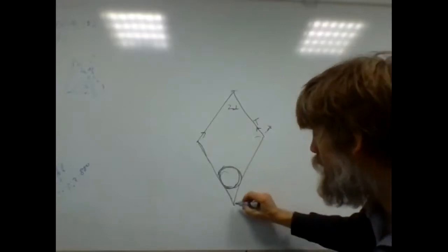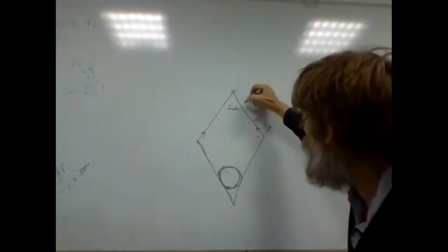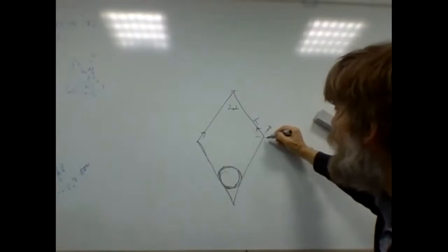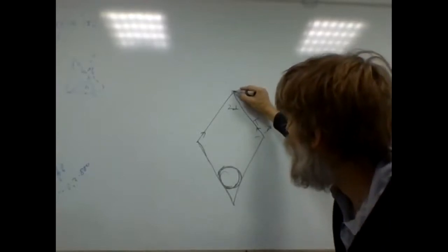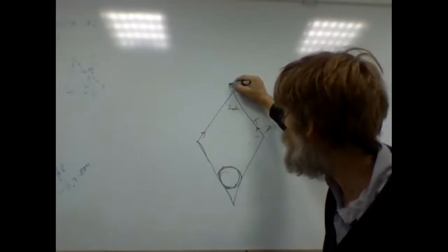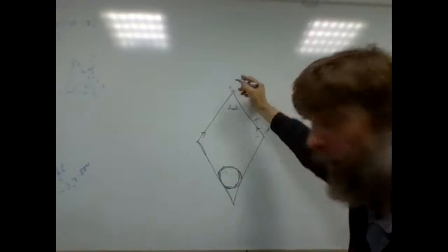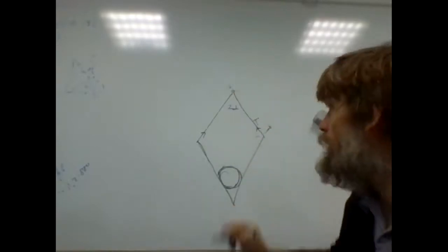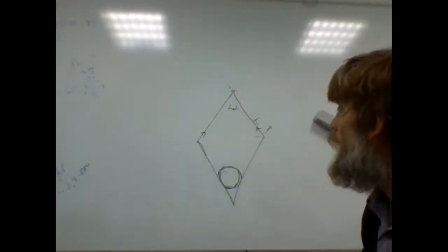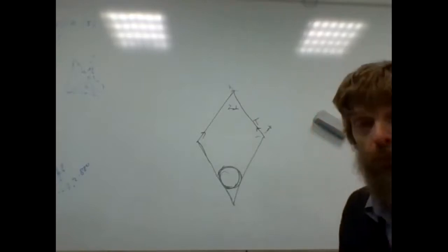That we have here 3 forces applied, one here, and one here. Here you can say that it is along the rod, because this hinge does not create torque, but only force. Then we have torque, force applied here and force applied here, and this rod must stay at balance, so the sum of torques must be 0.